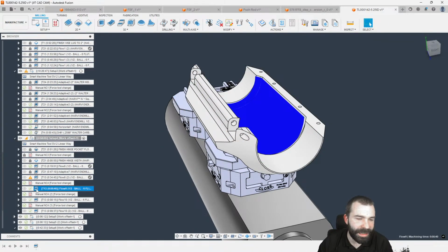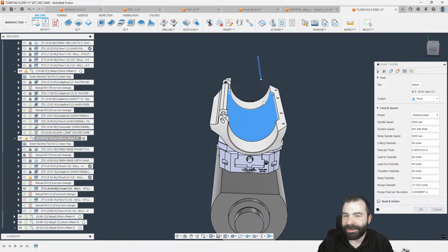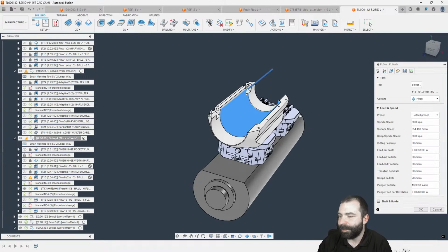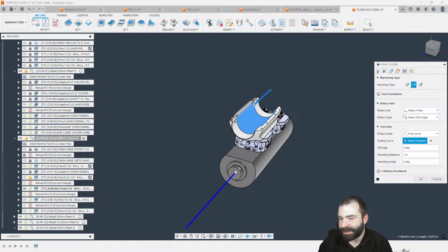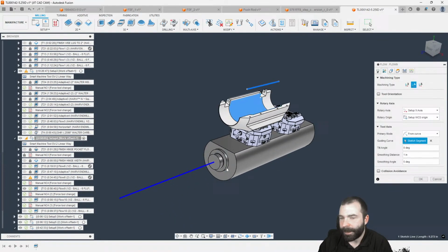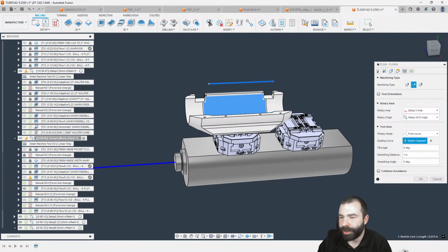And then there was a sketch that we were using, wasn't it? Yep. As you guys can see, as I was hastily trying to draw in Travis's case, we did the sketch of the line. And with the sketch of that line, we actually have that ability when we did our multi-axis setting. Again, we have our setup X. In this case, his X is around center down here. And what we're doing is we're swinging that part back and forth. And then because we used from curve, that sketch is our curve that we're projecting our tool down with, right?